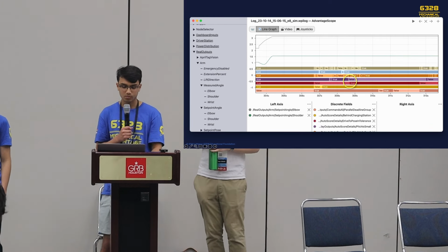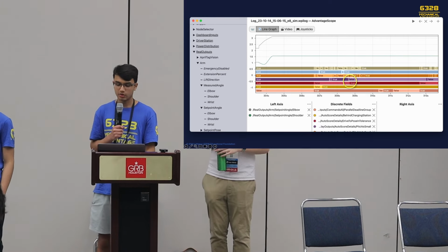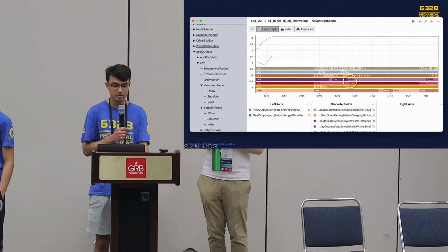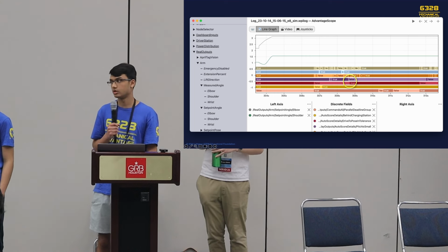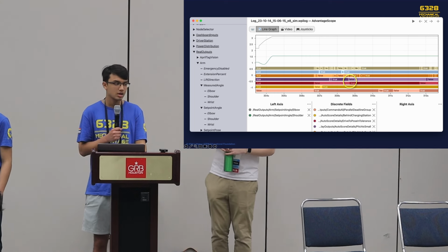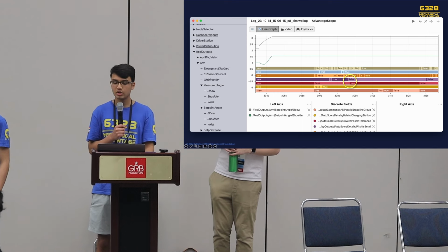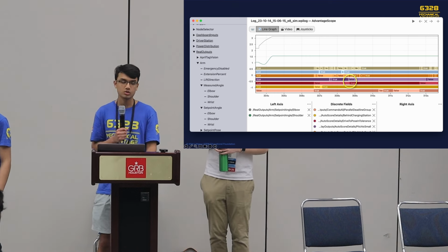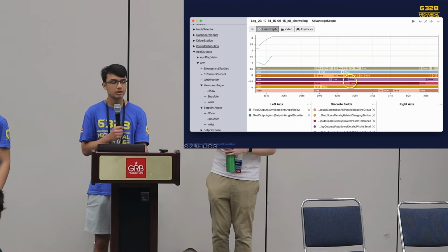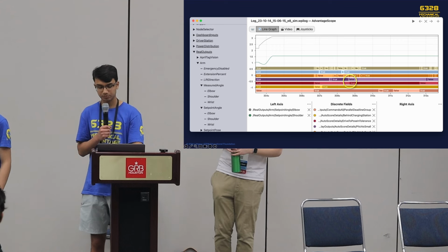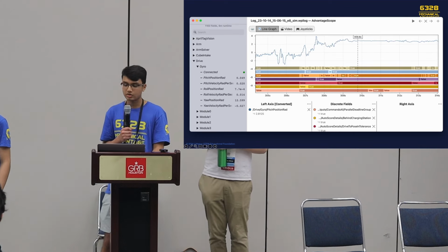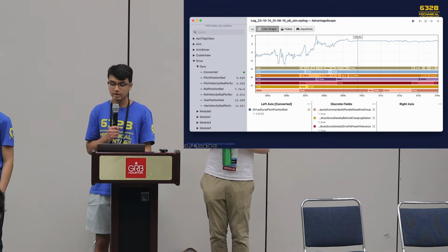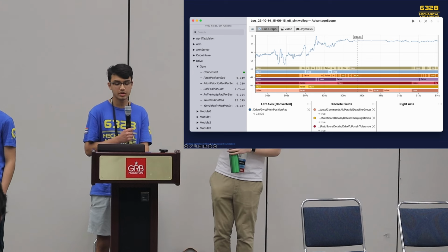Notice right here. The red shows when the pose is in tolerance, 1.2 meters and 45 degrees, and purple shows when the pitch angle is in tolerance, 2.5 degrees. Just as we're getting close enough, the pitch changes too much and stays that way, so the arm doesn't extend. Let's take a closer look at our pitch data. The pitch settles around 2.8 degrees, just outside of our 2.5 degree tolerance.